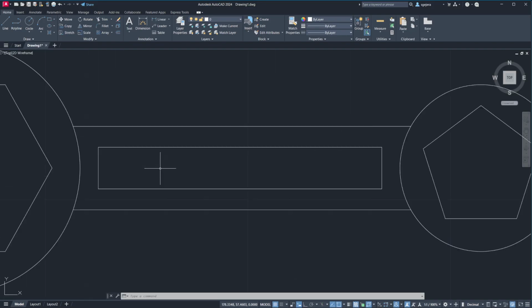So what we want to do is I want to access the fillet tool. The fillet tool is accessed through F. So fillet. Now before you select objects, kailangan muna natin mag-input ng radius. Okay? So to input a radius, we can go into the bottom and click the parang chips na to. So pwedeng click ko yung radius like so. Pwedeng left click siya. Pero for me, it's much easier to access it through the shortcut, no? And the shortcut is, again, kung sino yung naka-capital letters dyan. So, ang naka-capital dito is si R. So, I press R, then enter.